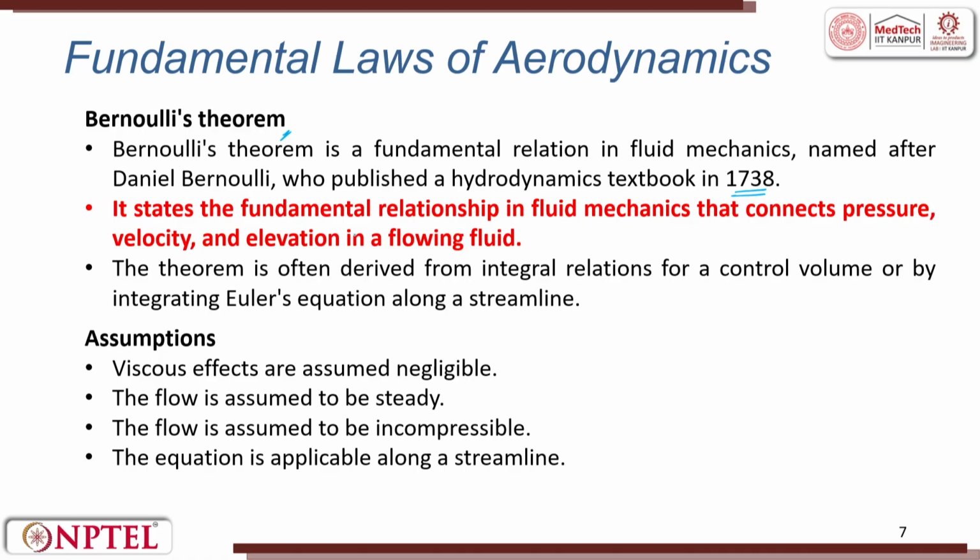It states the fundamental relationship in fluid mechanics that connects pressure, velocity and elevation in the flowing fluid. The theorem is often derived from the integral relationship for a control volume or by integrating Euler's equation along a streamline. We saw what is streamline, streak line.